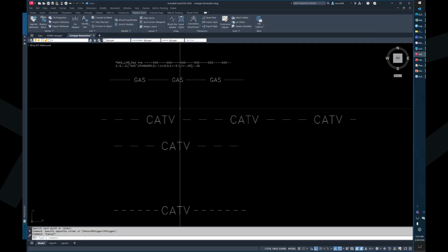You can do it in Civil 3D. The big thing is you have to make sure you're 1-to-1 annotation scale, and then when you draw it out, go back into the line type definition and confirm that it didn't create it with multiples of 10, because Civil 3D tends to work in feet, not small units.